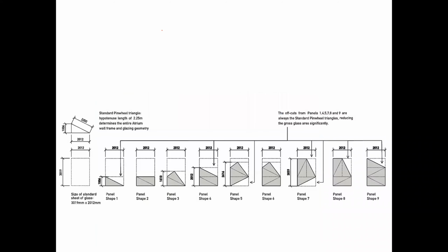And basically what they did is they found the optimum shape that both glass and sandstone and the aluminum panels or zinc panels that they were using come in, right? So they found one standard shape and size that all the materials they were going to use for the envelope would come in, like one module. And then they figured out how to cut those modules up into thirds, and how to take each of those thirds and diagonalize them into triangles. And how you could take a standard module, cut it up into a set of standard triangular modules, and how those modules can then be deployed in both repeatable and non-repeatable patterns, right?